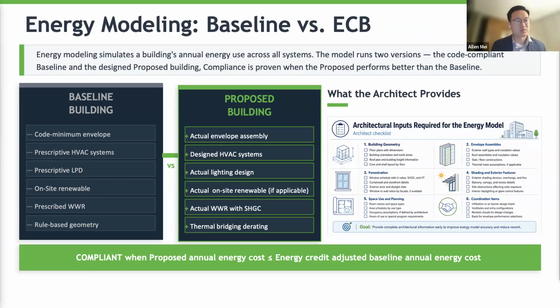So what is backstop? Backstop is basically, in the past, when you run a modeling pass, even if the wall has no insulation at R0 and the roof is like R20 versus the baseline R30, as long as the model passes, you pass. And we received a lot of concerns about that approach because you could literally trade off more efficient MEP system with a bad envelope, right? So in 90.1 2022, they added an actual layer only in the performance pass. It's not anywhere else. Only in the performance pass in both ECB and PRM.